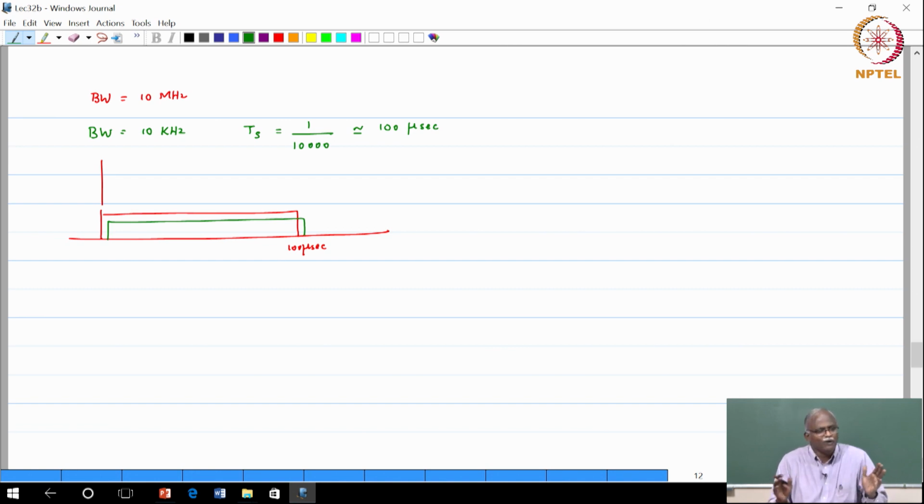Well, some small disturbance is there, but it is not from something which is 100 symbols away, it is my own symbol which is just delayed. So how much inter-symbol interference will you get? If the previous symbol was transmitted as purple, you will get some small contribution from the previous symbol. So this is a case where ISI can more or less be ignored. You can treat it like noise and say, it is some small impairment.